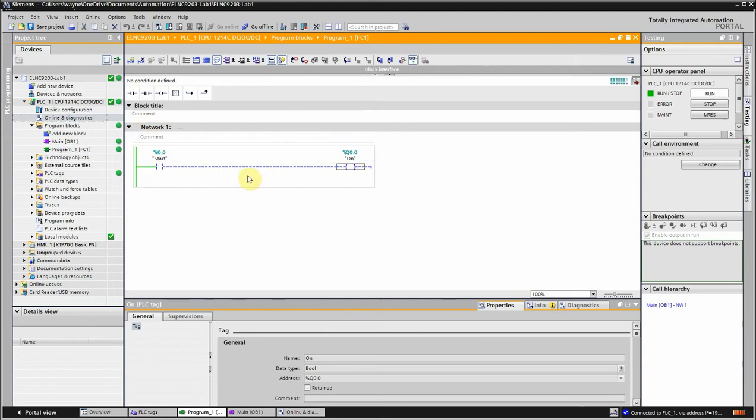Now you can see we're showing up as blue, being off, and the power is being stopped. This is kind of the way it's showing here. Right, power is coming down this left rung, showing as green. It's getting stopped at my examine if closed, or normally open, contact. So if I go down to the switch and I turn the switch on, okay, the light on the input turned on. I have the output turning on on my screen, and the output is turning on on the PLC.